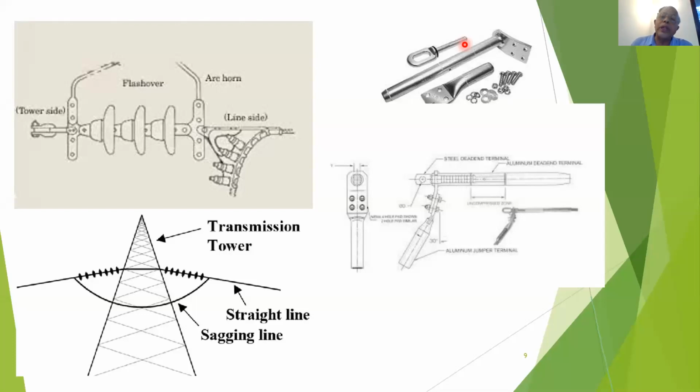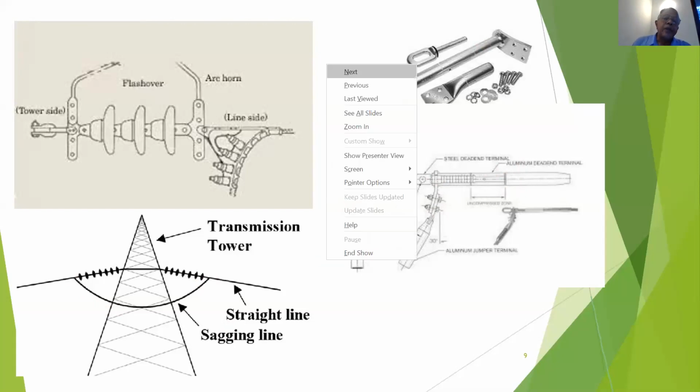So that core is connected over here, and it's going through this because, okay, you can push it now to this side, so it comes over here, and in this part the aluminum part is crimped finally. Then for the jumper you get this one, crimp it here, this lug, and connect it, and then you have the jumper. So these are the conductors.